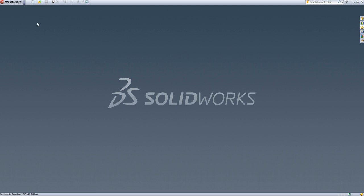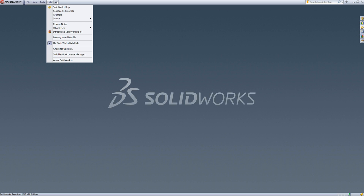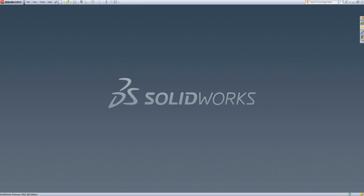You'll notice up in the top left-hand corner there are no menus. The way this works is you'll see where it says Solidworks in the top left-hand corner, and there's a little arrow that pulls to the right. As soon as I put my mouse cursor on it, it does automatically open. What we want to do is go right to the end of it and click on the thumbtack so the menus stay. Now we still don't see a CheckMate menu here at all, and of course no icons.